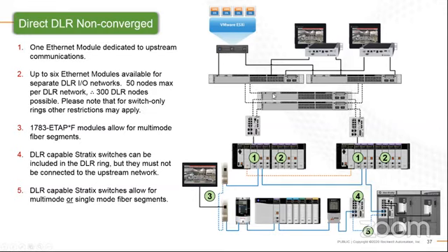North of that, anything that happens at the distribution switch layer does not affect your redundancy swap over. So as long as this connection here is solid and this connection here, you won't see any intermittent swap over events. So it's typically why we try to have a dedicated switch up top.